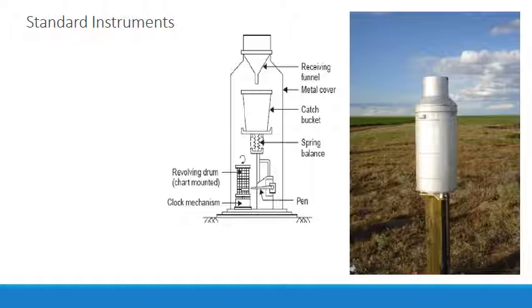Also, wind can lead to measurement errors by either causing too much or too little precipitation to enter the collecting container. In addition, because rain gauges provide data for a specific location, the significant variations in the amount of precipitation that reaches the ground over a whole region can't be estimated accurately.